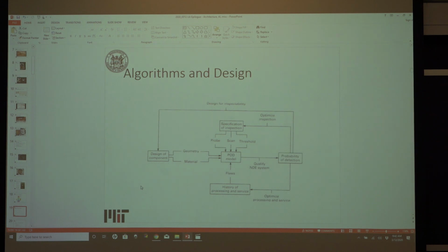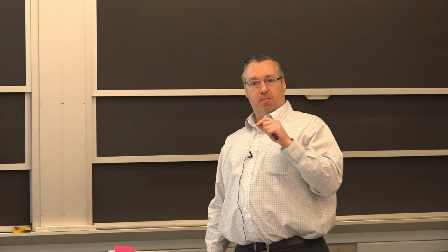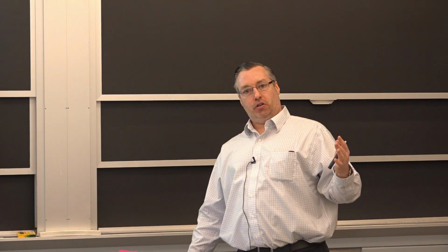This is used for non-destructive evaluation, what would be known as probability of detection models. So for structural components, for aerospace, for nuclear, for bridges, where you need to predict how long you can keep that bridge in service until the next inspection, they use these POD models to determine inspection intervals for 100% critical infrastructure.